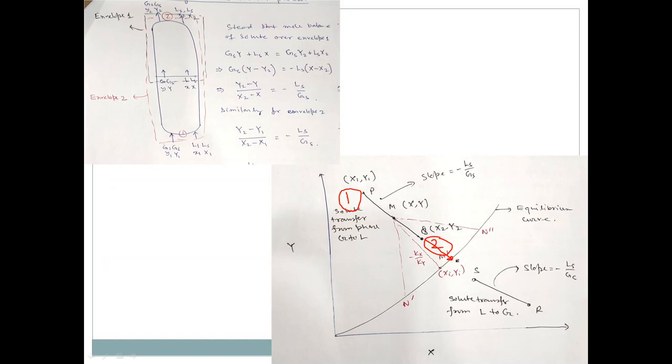But after that, if you increase the height of this column, nothing changes, because it has reached equilibrium, and thereafter no mass transfer will take place. The corresponding exit concentrations will be these x and y.